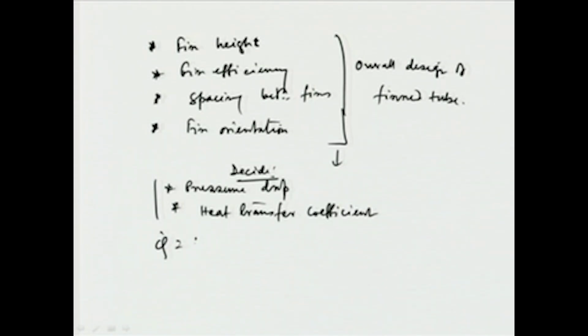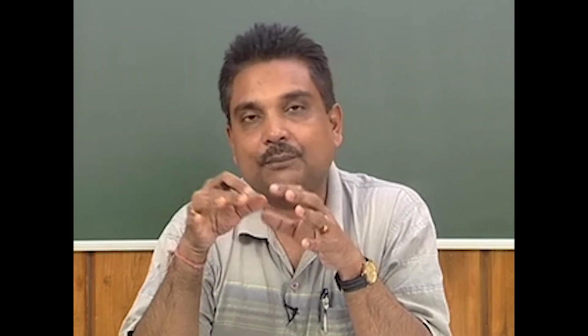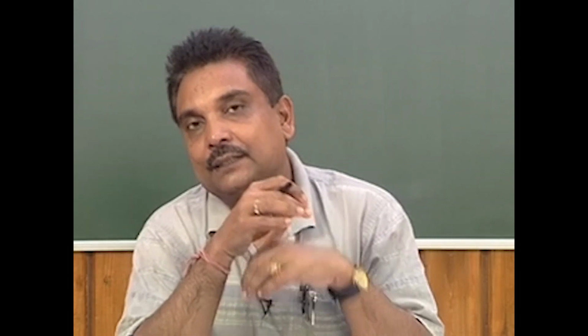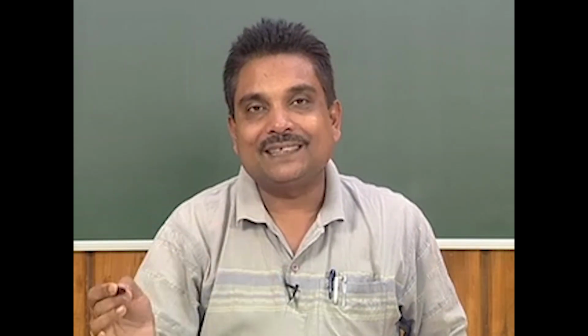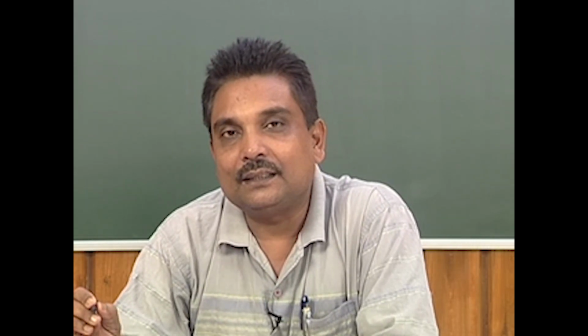And then depending upon that we can use, as we have discussed, the rate of heat transfer Q dot equals U A delta T, and as I told in the last lecture, U is the overall heat transfer coefficient, delta T is the temperature difference, and A is the area of heat transfer. When the fluids are airy substances, say if we have to extract heat energy from air, or if we have to cool some body, then the air to metal surface heat transfer coefficient, or for any gaseous substance, is very small compared to the liquid side one.